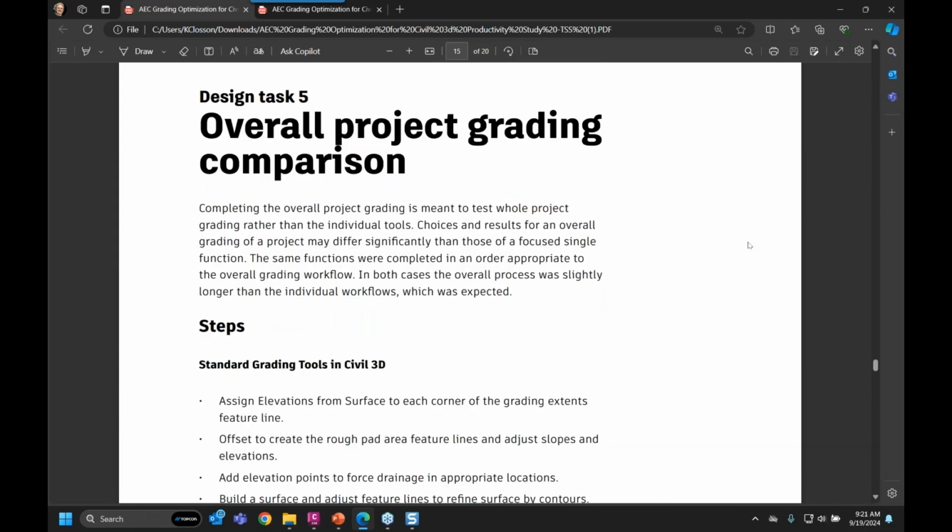Again, I didn't go through these two in depth because I know you guys can read them on your own, but the big thing I really wanted to highlight is how much work goes into that. Now, again, I don't want to lie to you. If you do this, it may not come back as anticipated. If it doesn't, that's where you can go back into it, maybe make some changes, swap zones around, whatever. Say try to do the parking lot before you do the building pad that's associated, or whatever it may be, and you'll quite possibly get better results, and then going in, we're going to start doing the more granular grading as we play with it.